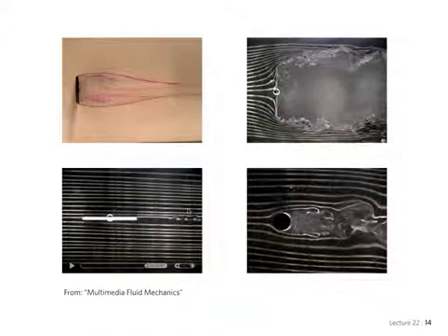A horizontal plate will have a very, very small wake, and if the thickness was 0, the pressure drag would be 0. But there's always, in real life, some finite small thickness. But most of the drag will be friction drag. In this case, we have another blunt object, a cylinder, and you can see again the separation for that case.